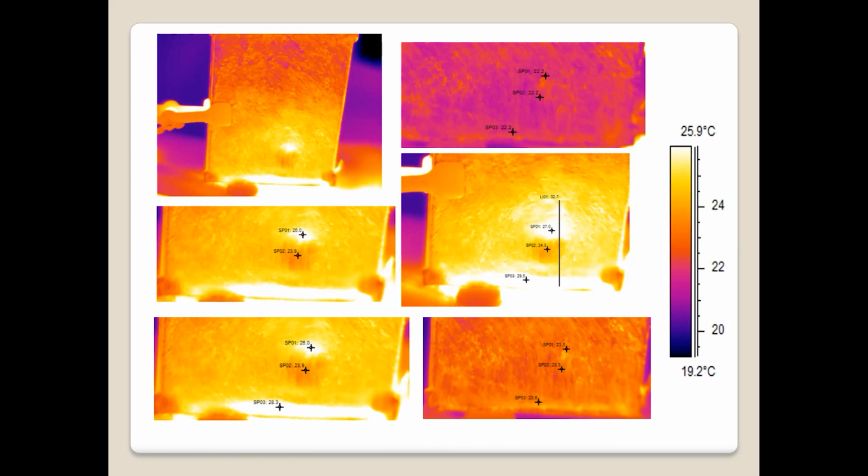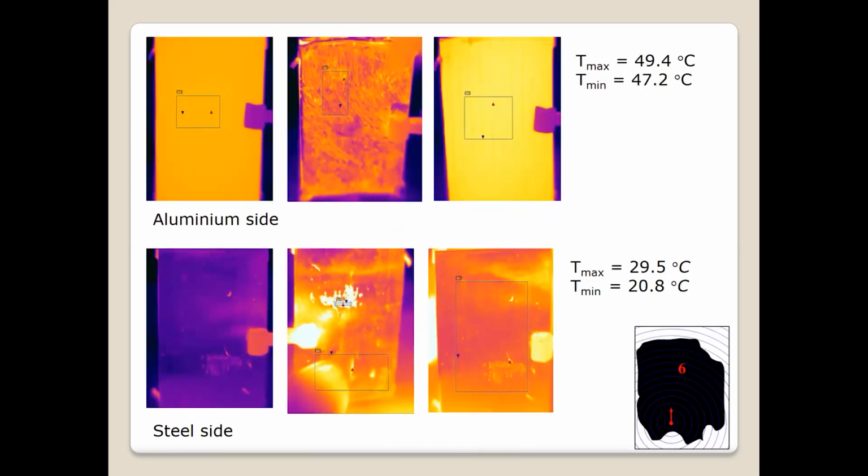But on the other hand, further, when we have recorded after several more frames and during the time when the cooling of the sample was taking place, we could observe different behavior, just like in the ultrasonic method. Near the edges and near the place where the standoff distancers were placed, we could notice the areas of non-welded material, and not only displaced with the mechanical deformation which I mentioned.